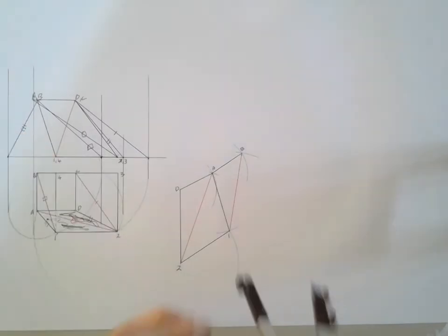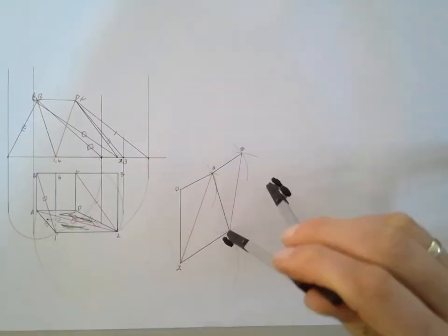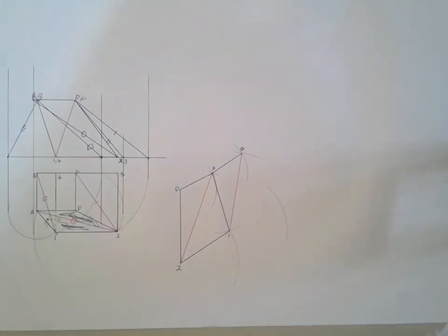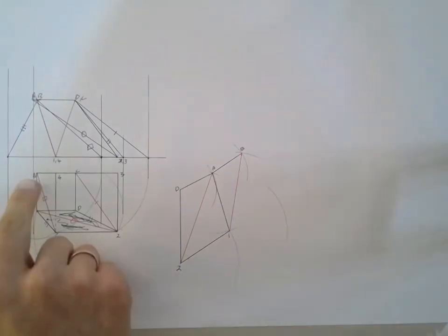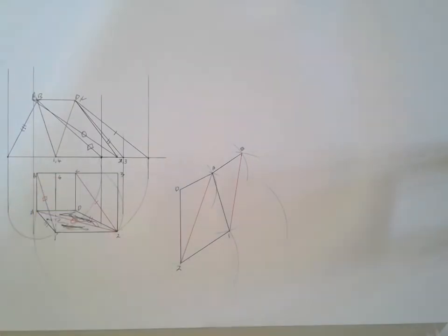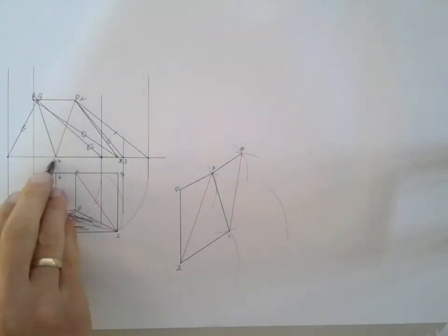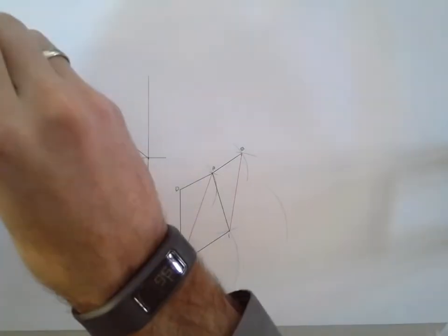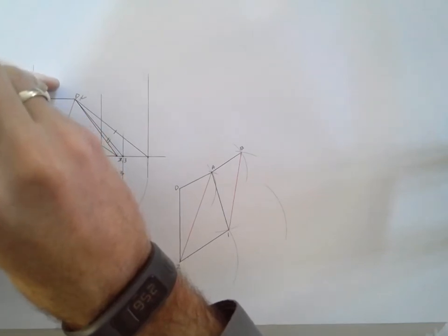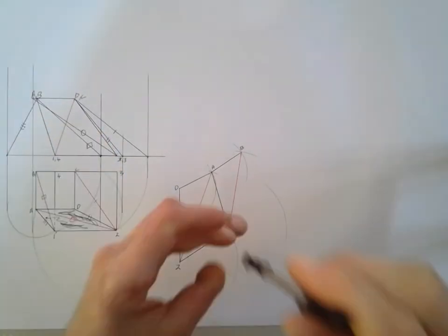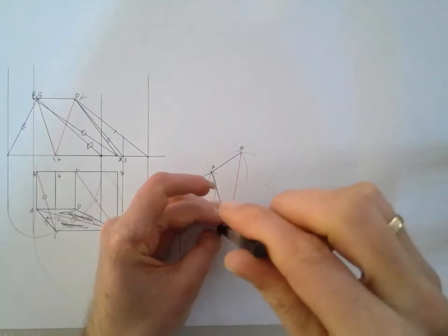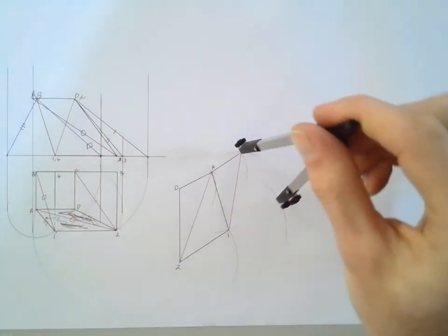I place that on point 1, make an arc. Then I go and take the true length of line B4. Now line B4 belongs to that vertical face. And as soon as a line is vertical in our top view, in the front view, that is its true length. So I can just go and find the line B4 in my front view, the original B4, and I can take that length, because I know that that's going to be its true length, and I can take it and place it onto point 1. Sorry, not onto point 1, onto B.